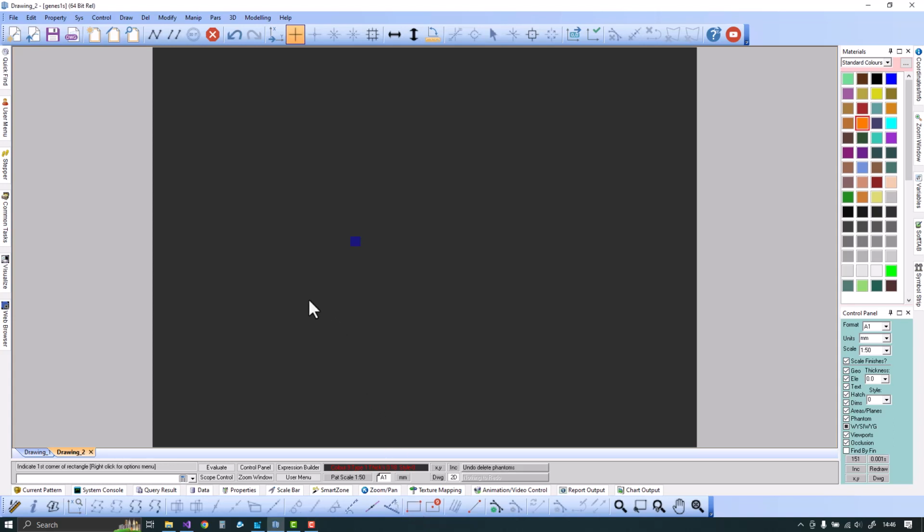So I'm going to draw a rectangle over here, starting at that corner there, 600 wide by 1200 high. I'm going to then draw something that starts 1000 from there and 2000 in Y, and then I'm going to step off from a point over there. We're going to go left 1000 and down 2000. So that creates two rectangles, one within the other.